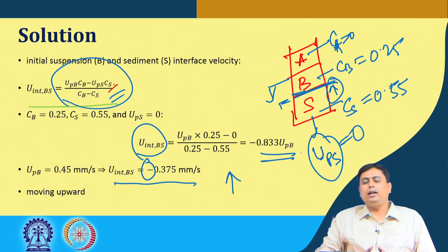If it's indeed in that region, then we can go ahead with the value of n for the Stokes law region. Otherwise, we have to use the appropriate expression in the other regions to calculate the Ut, that is the terminal velocity for a single particle.